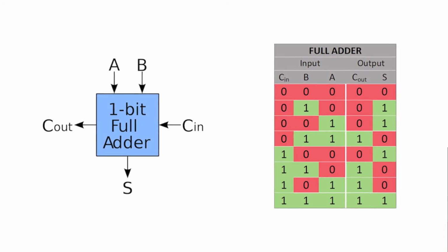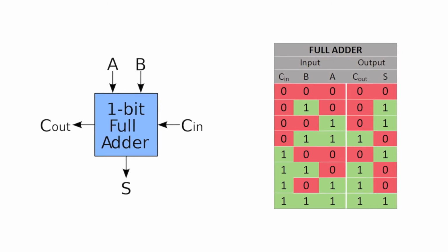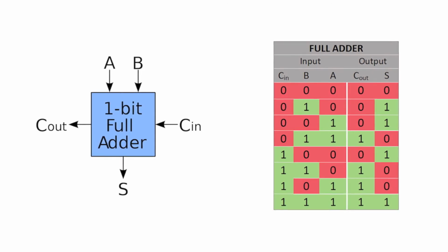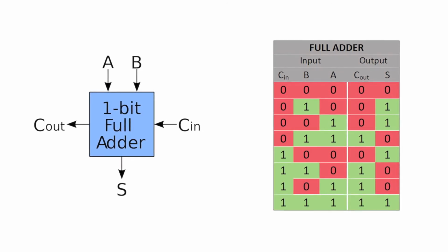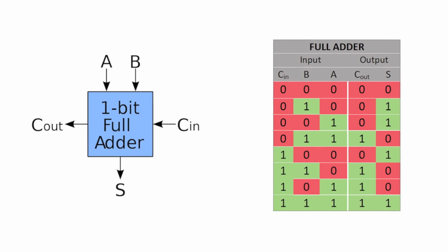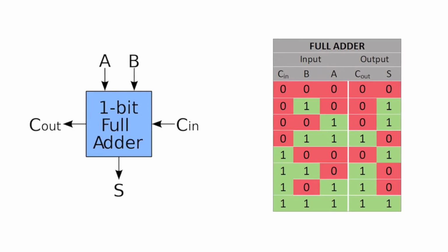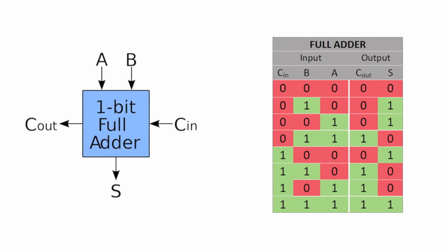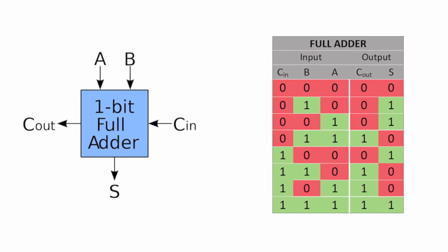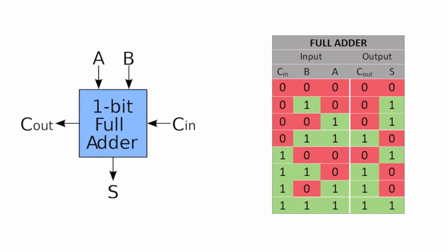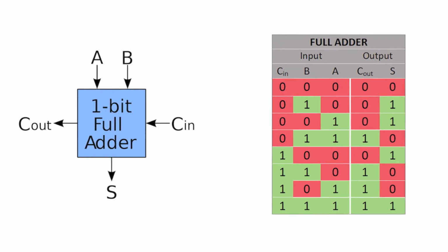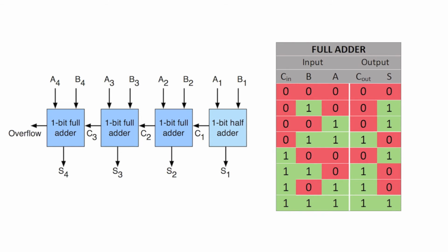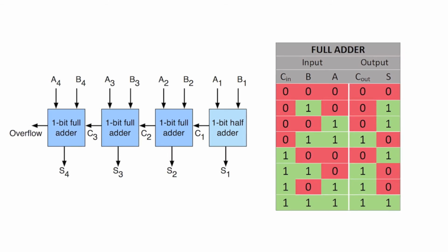Full adder. A full adder adds binary numbers and accounts for values carried in as well as out. A 1-bit full adder adds 3 1-bit numbers, often written as A, B, and a carry in. The carry-in bit is used when more than one full adders are linked together to handle multi-bit input. Here the carry-in bit is the leftmost switch. It has two outputs, sum S and carry C. The carry signal carries the overflow into the next linked adder.